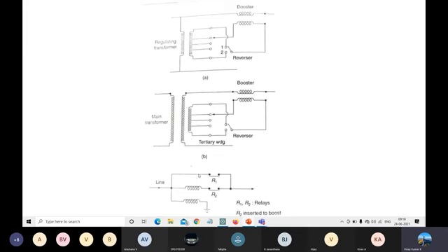So R1 and R2 are our different relays. Depending upon the required amount of voltage levels, we can open or close these relays. Okay. So this is our transformer winding. We are placing these windings along with the line. So if you are interested to insert one terminal of the winding, one booster transformer winding, at that time R1 may be opened.